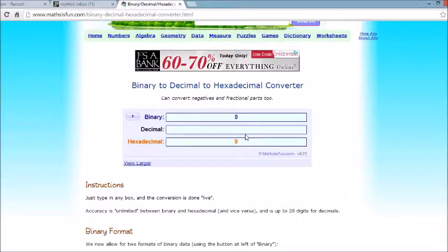But this is where it gets tricky, once you start going into the 10 through 15 range. This is when numbers become letters. Now this is 10 because in binary it uses all 4 of these digits. So you have 1, 0, 1, 0, which translates into 10 in decimal, and A in hexadecimal. So to see the full range of this capability, you start with 255.